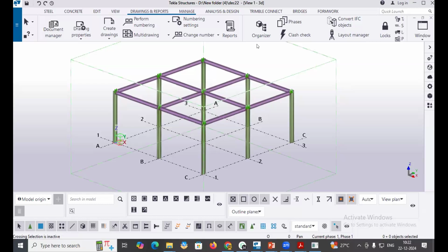And right now Tekla is also doing R&D to make an all-in-one software. But every software has pros and cons, and Tekla also has some, because it is not able to extract each and every force we want from a particular design. Like in STAAD or ETABS, we can't get the reactions very exactly, because you can only get exact reactions when designing the project in centre-to-centre design.